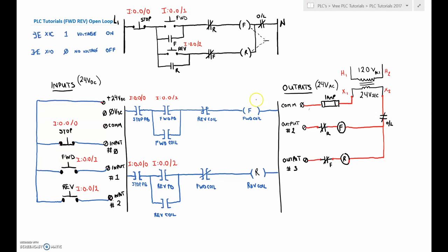And so we'll address these guys for our outputs, and then these two holding contacts are going to be addressed the exact same as the outputs. So when the output turns on, then we'll look for the presence that something is actually turned on. So we'll look at the same address there. And it's just looking in the PLC program to see that that output is actually turned on.